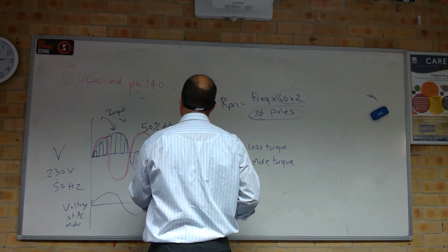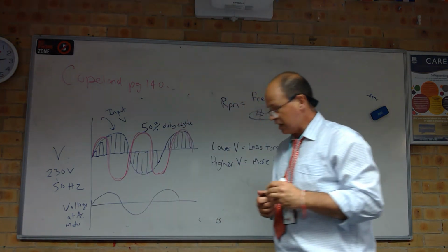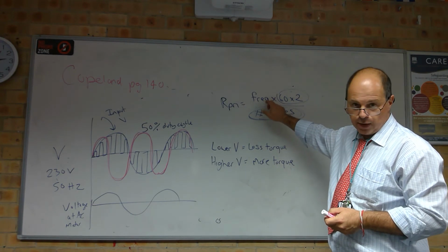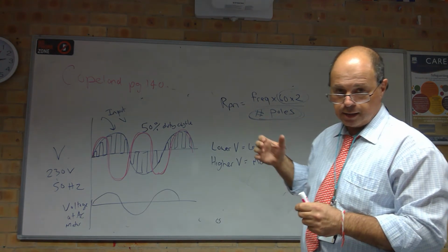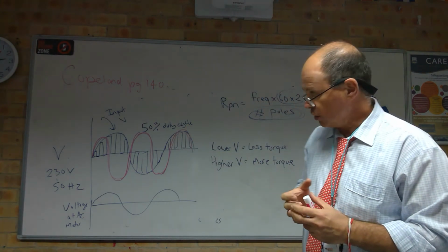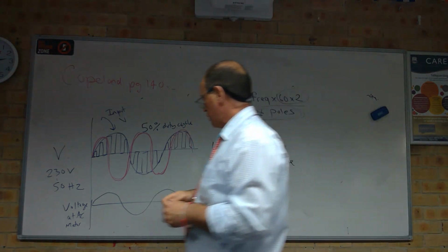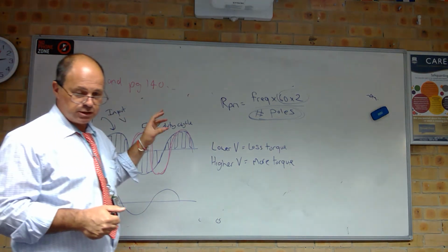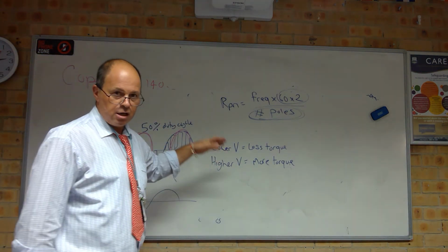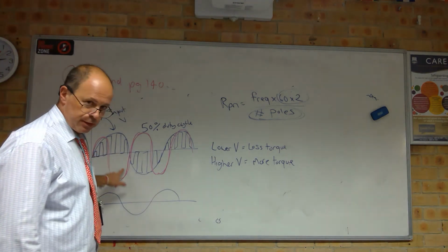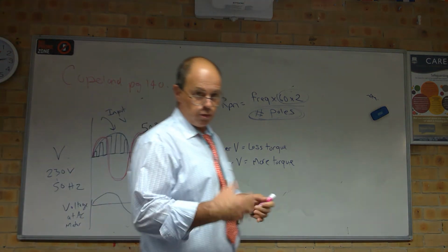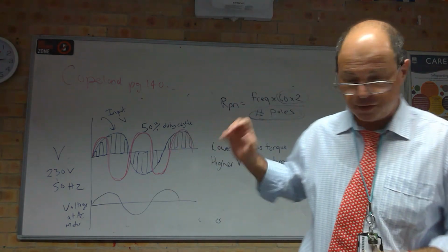So we've doubled the frequency. By doing that, we're allowing our RPMs to go up, okay? So there's ways electronically to change the frequency, and that's why this is called a variable frequency drive, because we can change the frequency, and we can also chop up the voltage that's presented to the motor, with pulse width modulation to change the voltage.